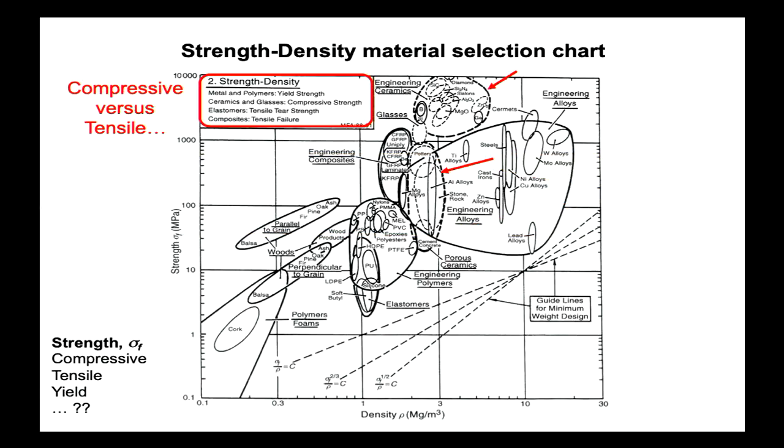Now, tensile versus compressive. I thought I'd put it in. I've done this in exam settings as well. It's a chain or a rope or a cable or some such. It's a tie, axial tensile loading, which means positive stress, which means that all the ceramics become invalid, because that dashy line and what's written in there: ceramics and glasses, compressive stress or strength only.